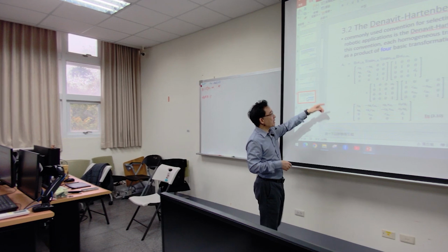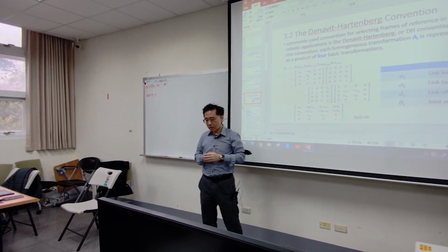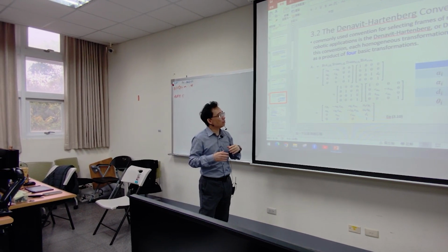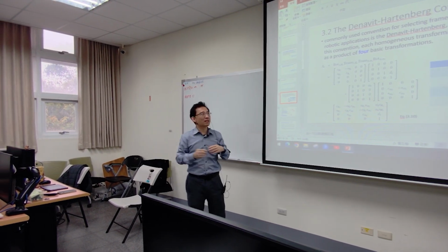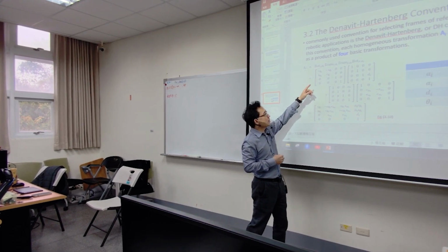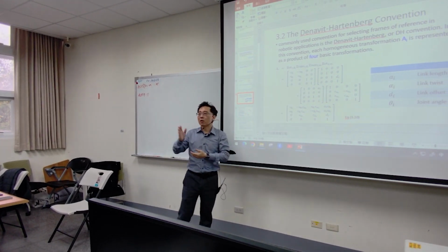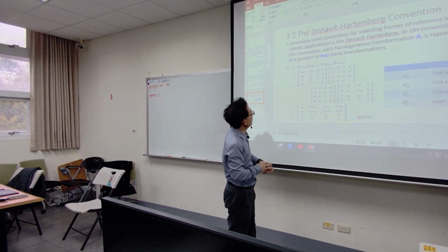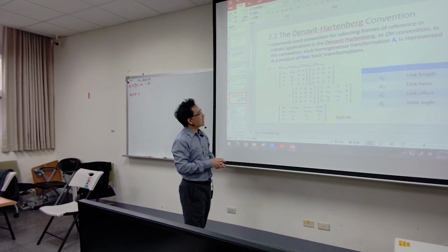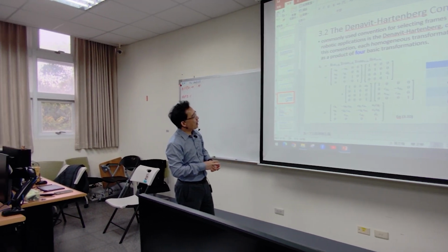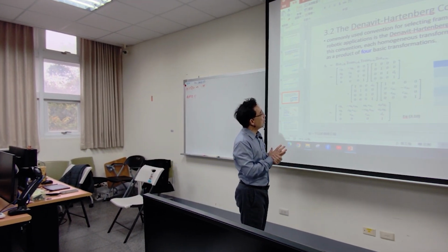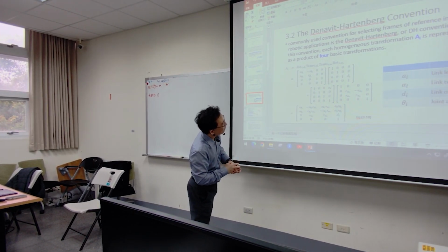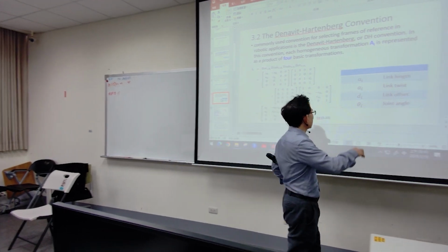Over here is an example. We have a rotation along the Z axis with theta, and the translation along Z by d_i. This is called d_i. And the translation along X by a_i, and the rotation along the X axis with alpha_i. Oh, a and alpha are so confusing.